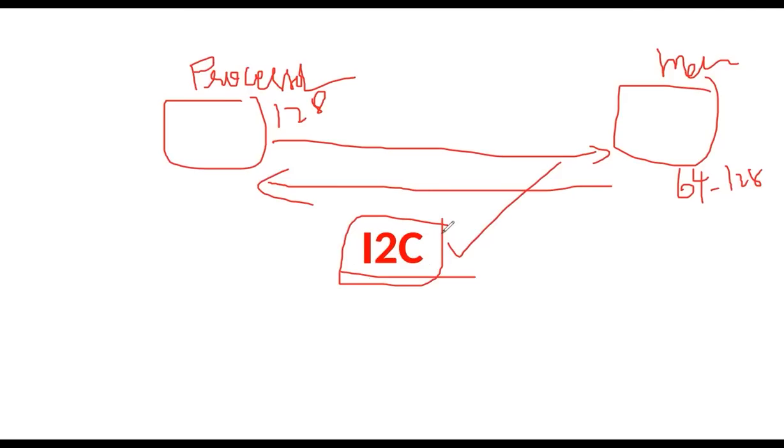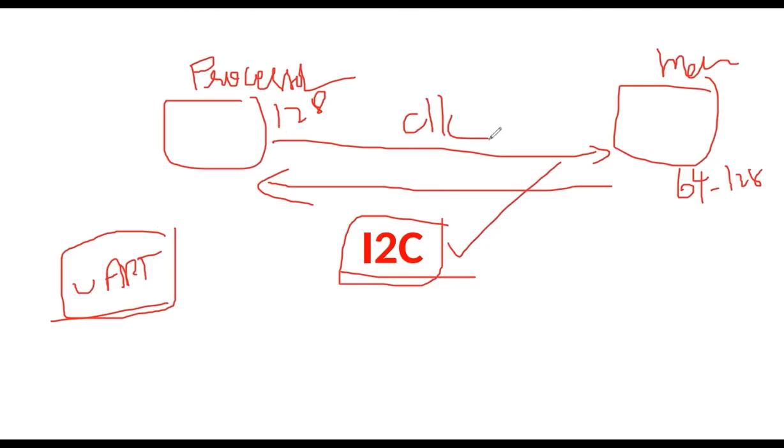Okay, and what is the next rule, whether it is synchronous or asynchronous? What asynchronous protocols do we have? UART. UART is an asynchronous protocol. In this, we didn't use any clock, right? Based on the baud rate, we generate the UART. But for other protocols, baud rate is not good for synchronization. We cannot provide more synchronization between the transmitter and receiver. That's why we use the clock. So here we need to check the clock also, along with your address and data. Okay, so these are all the rules we need to follow.